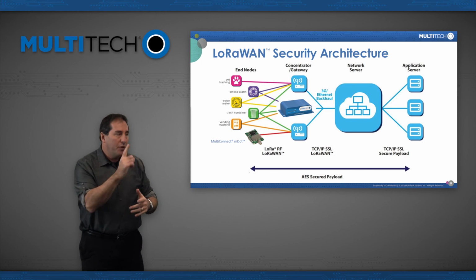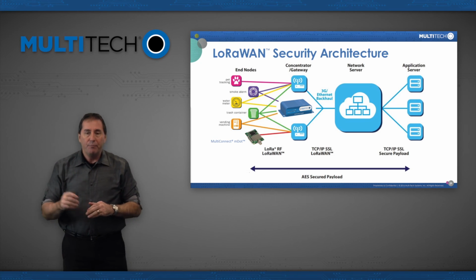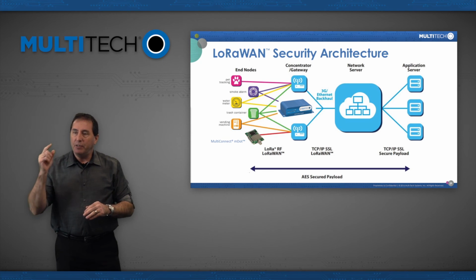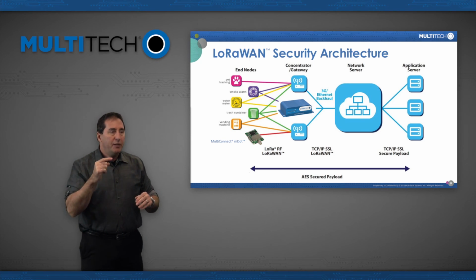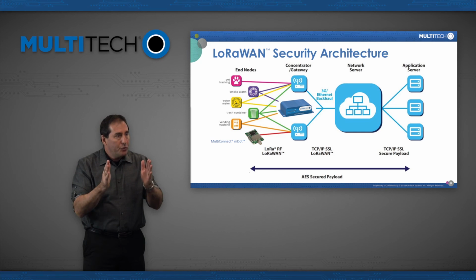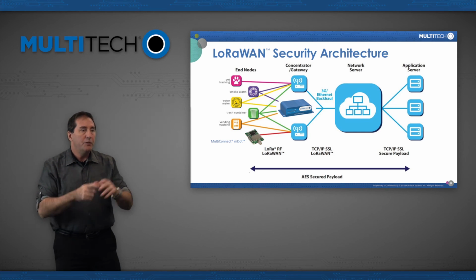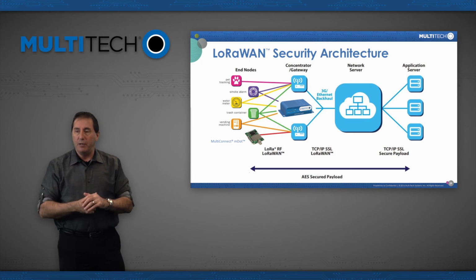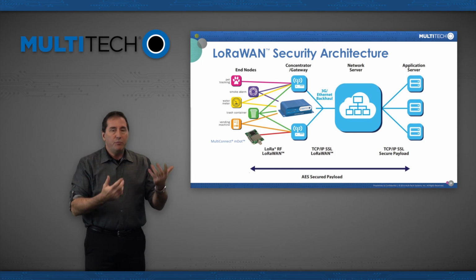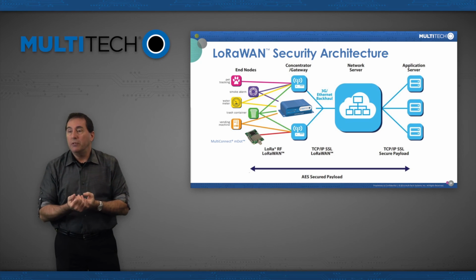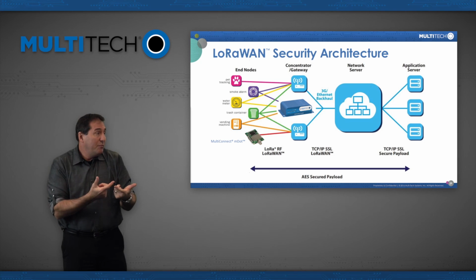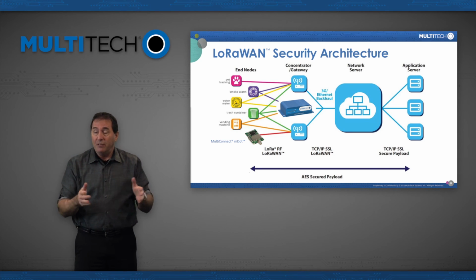And there's one other quick thing I'll mention about keys. This would all not be very good if these keys stayed in use for long periods of time. So with today's LoRa network, until 1.1 comes out, you do a join, you could go years without rejoining the network. That means your key would be the same because it's a session-based key.